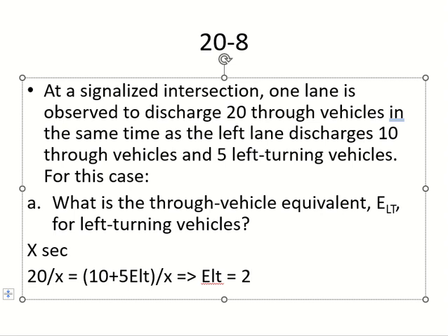For any situation, you just need to compare the vehicles of one direction with the other direction. That's it. Clear? But the only condition is if you are comparing between two queues, these queues should be continuous. In one lane, 20 vehicles are going continuously, but in this lane I have only 2 vehicles. So the first 2 vehicles pass, the next one is coming after 15 seconds. You cannot add them now, there's already a gap. If you want to compare between 2 lanes, these 2 lanes should have continuous flow. The gap should not be included, right? Clear or not?